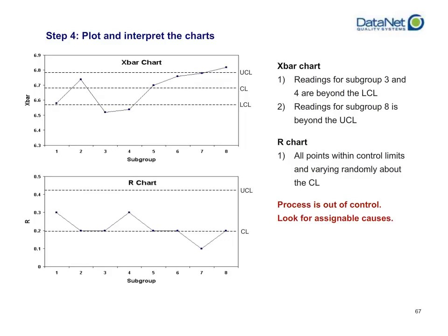We're also going to look at the R chart. You can see that all of these subgroups fell within your control limits. There are no specs for your range. Ultimately, ideally, you would want zero variation and you'd always want to hit your target. But since that is almost impossible to achieve, at least not in a cost-effective way, you want to get the volatility of your process to where it is within historical consistency. There are no points that fell out of control.